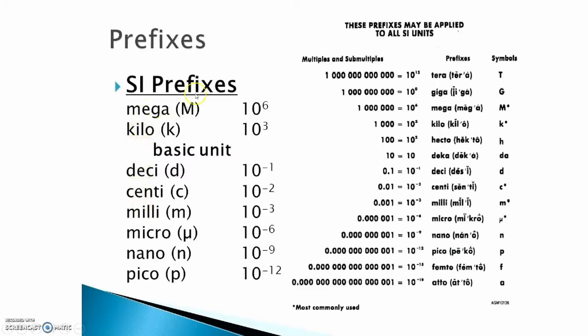So these you are used to seeing, but you need to remember to use them within electronics because often you are working with millivolts or milliamps, or you're working with kiloohms. If you forget to include this information in your calculations, you might get the right significant numbers but the wrong multiples.